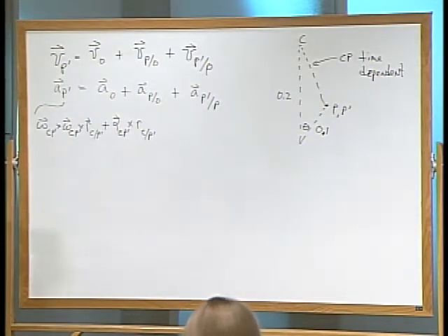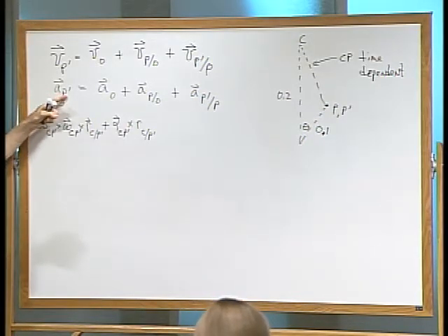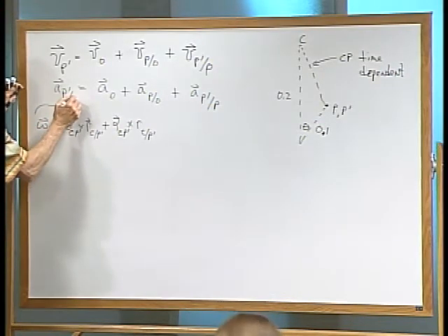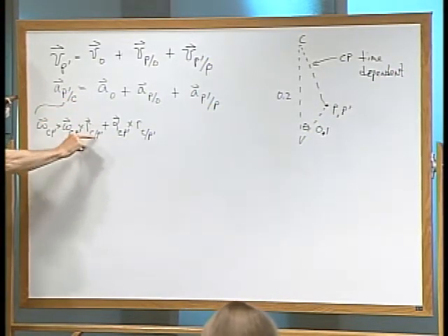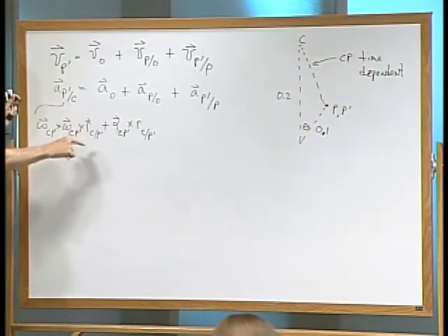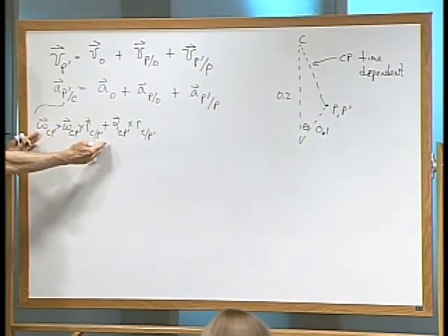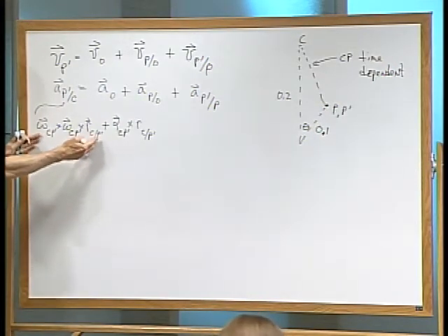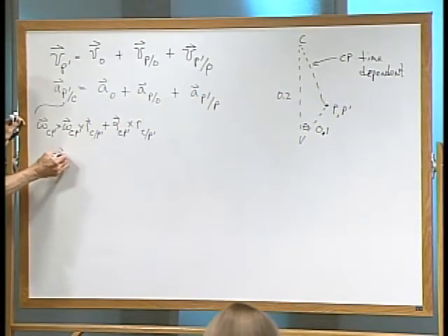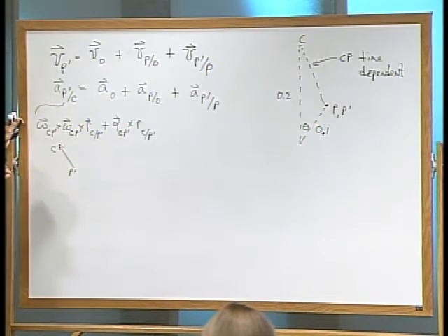You know, actually, I have this backwards, don't I? Acceleration of p prime is in reference to what point? It's in reference to its point of rotation. So to be safe, it should be that way, and I was able to catch that by thinking about it for a second. I would also catch that if I did my math and saw that this thing was not pointing back up towards C from p prime, right?